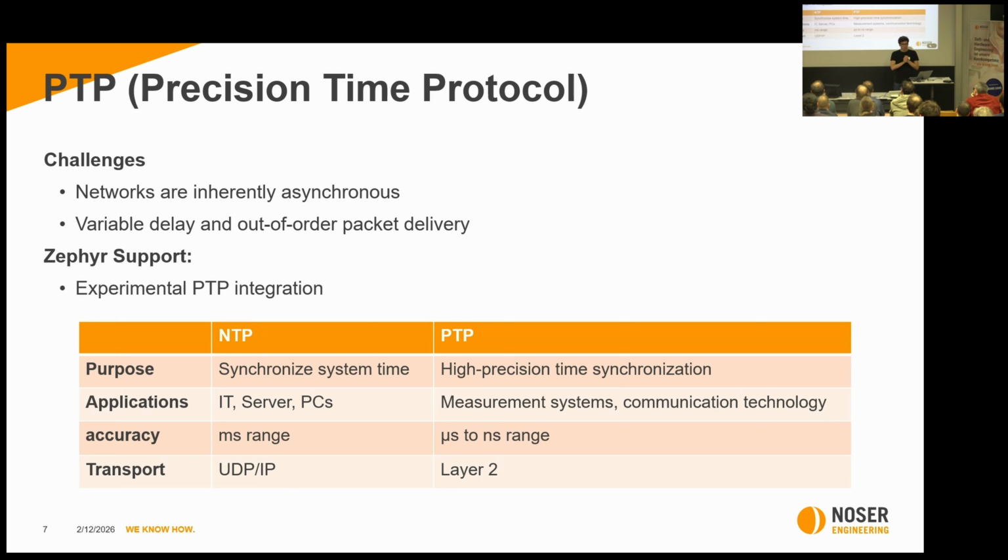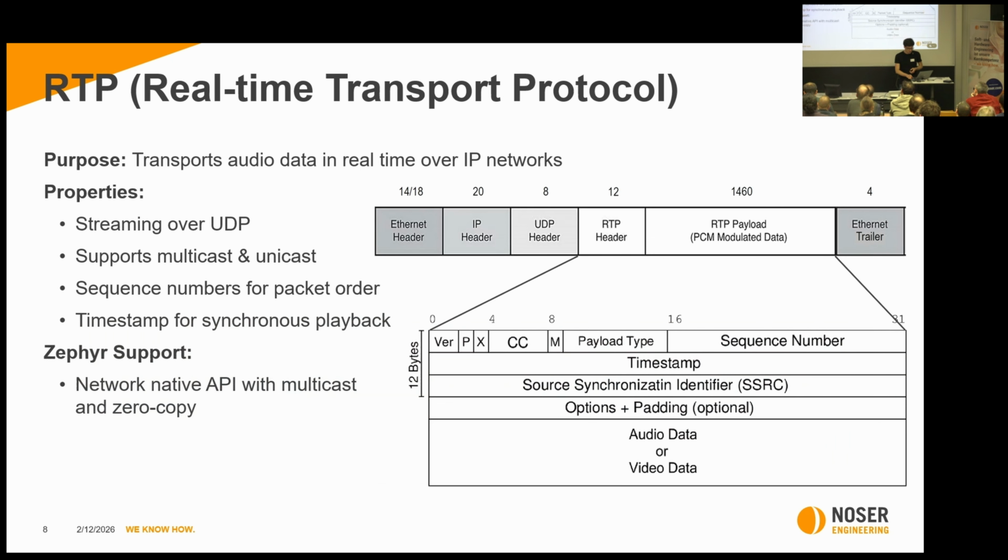If you want to use PTP with Zephyr, I can highly recommend switching to the main branch. I committed a fix regarding the Grandmaster mode. Now this one is working too. Synchronization is done. This already solves many issues.